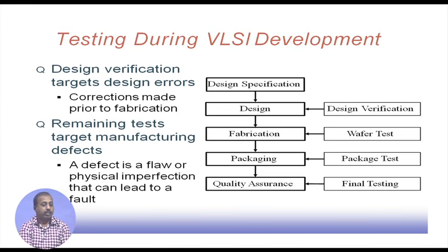Now, at that point of time, we need to check whether the transistors have been fabricated properly or not. As I was telling, if we can detect this wafer to be faulty at this early stage, some transistor to be faulty, we can remove this transistor from our connection pattern, and maybe we can use a substitute transistor for the purpose. So, at this fabrication level we have to do a testing, which is the wafer level test.